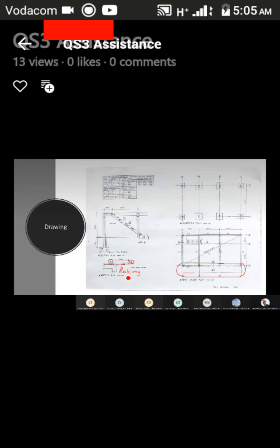Again, that is what I would use my bearing level, using my ground level as my bearing level, and my dimensions then would be 14.22, which is the overall length, from there, the outer side there, and multiplied by 1.5, which is indicated to me over there. I'm happy with my cantilever slab.